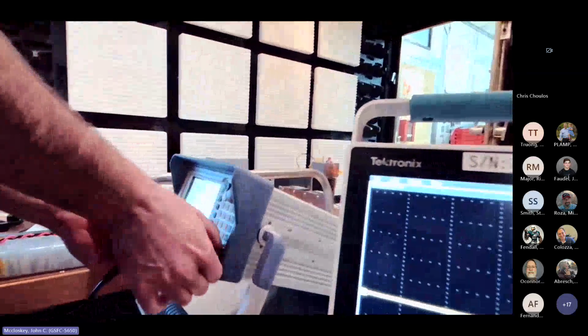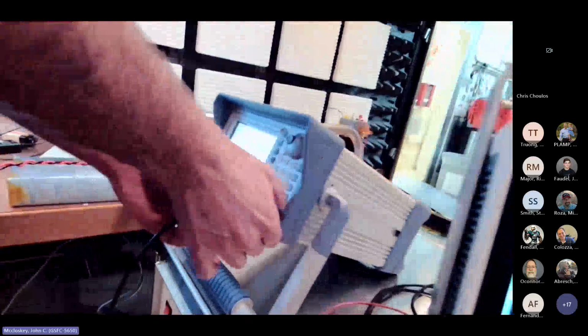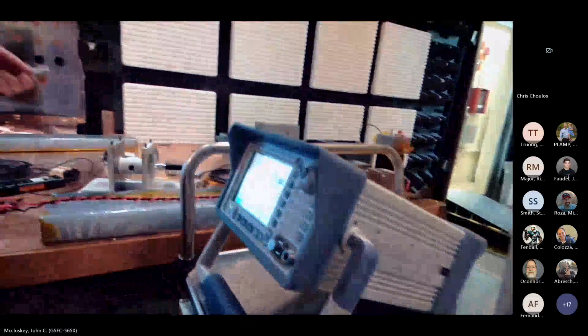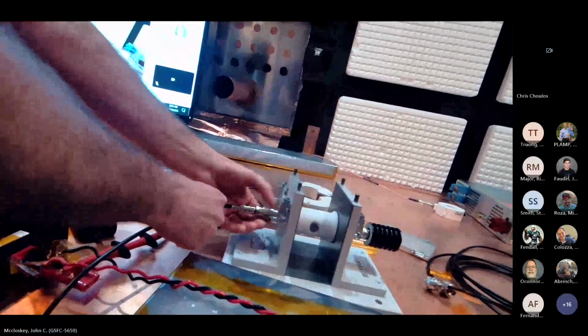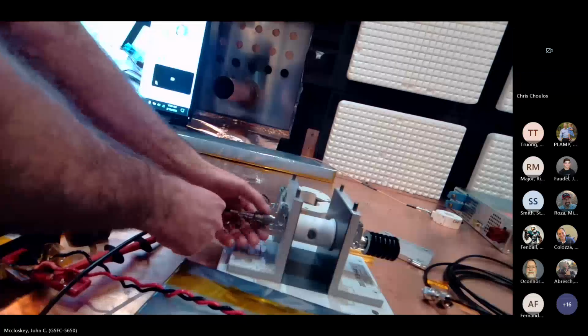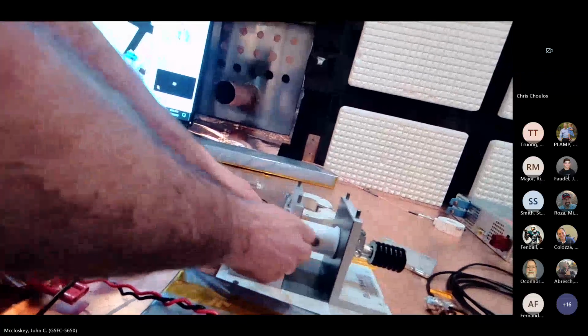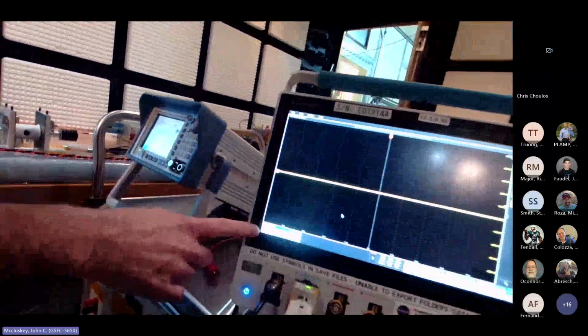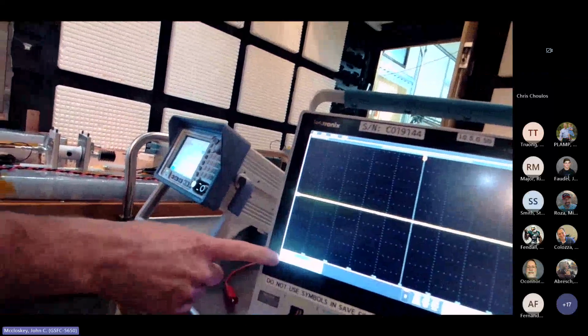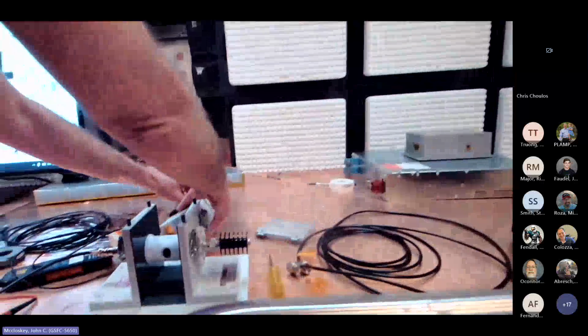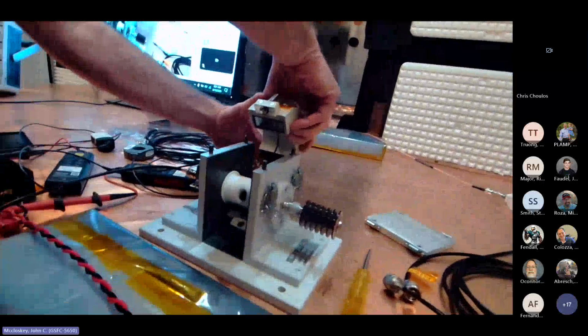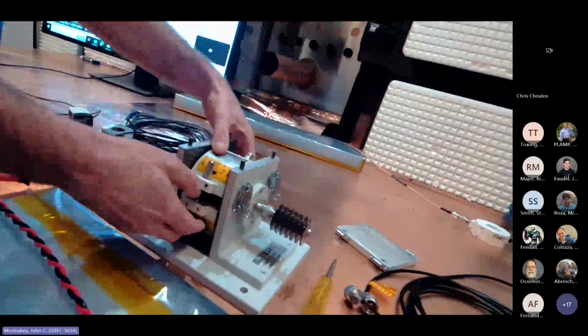So we're going to go from this cable to the output of the calibration fixture. I want to make sure the input, we're not running anything yet. Okay, the input, we're still going to be going into channel 1 for this next bit. That's still on the 50 ohm input setting. So that's what we want. And now we're going to put our injection probe into the calibration fixture.